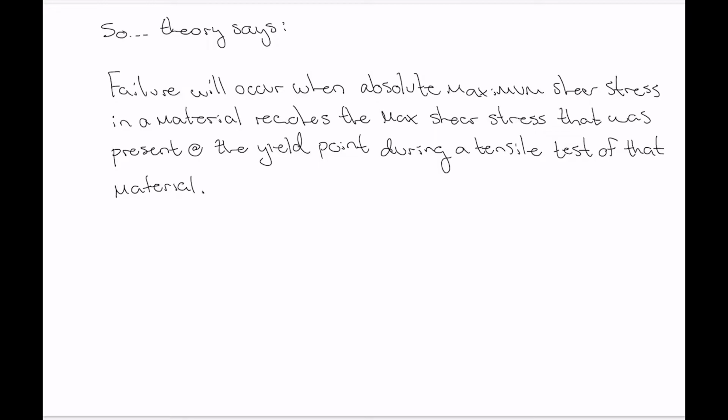Okay, so putting that into shorter form, we say that failure will occur when the absolute maximum shear stress reaches the shear stress at the point when the yield stress occurred, which we just determined was equal to the yield stress divided by 2.